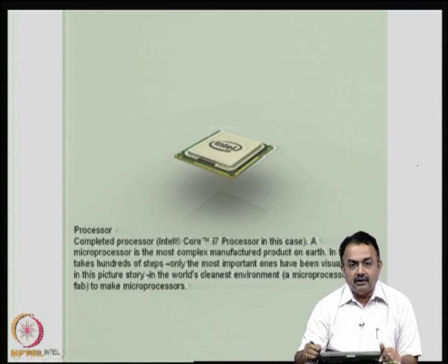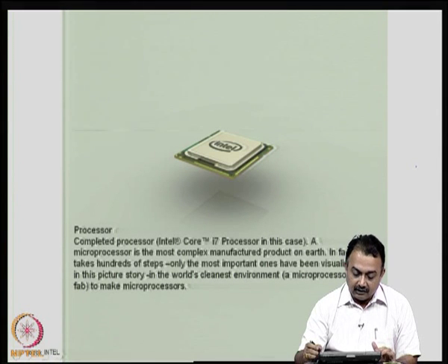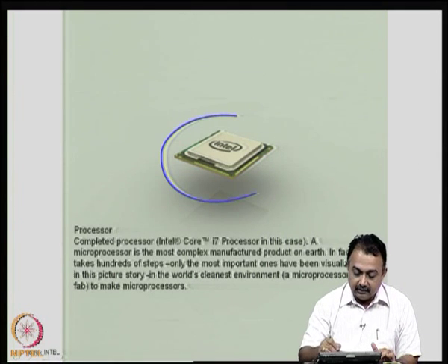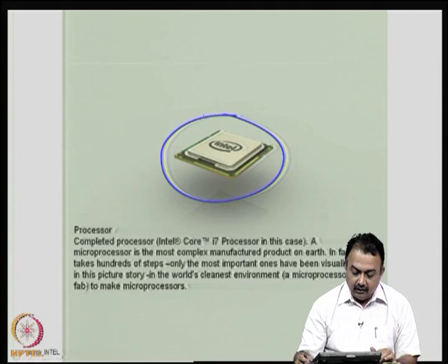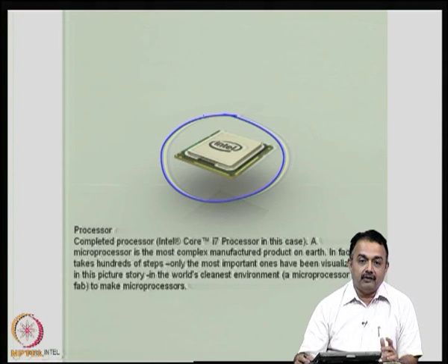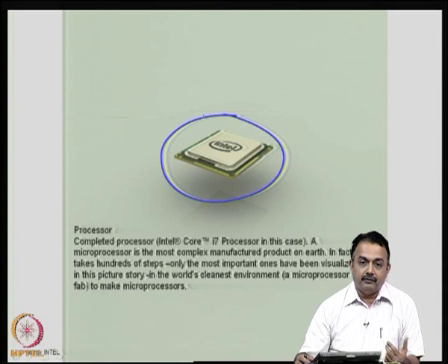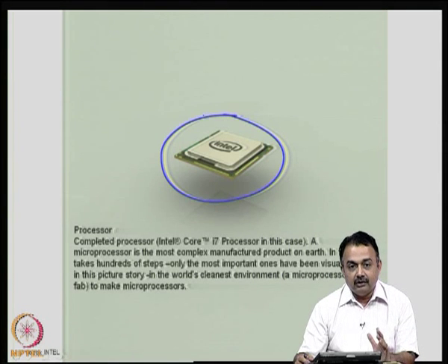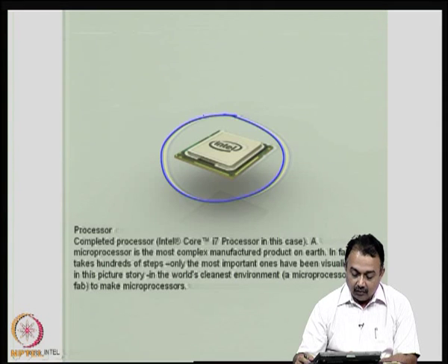Now, the processor in this particular example flow chart that we have been seeing over the last two classes. Now, the processor packaging is complete, right. What we have seen, the illustrations are very few, but in actual practice there are scores of sub processes that the wafer has to go through, including the back end packaging, die bonding, wire bonding and so on, to make sure that you get a more reliable package.